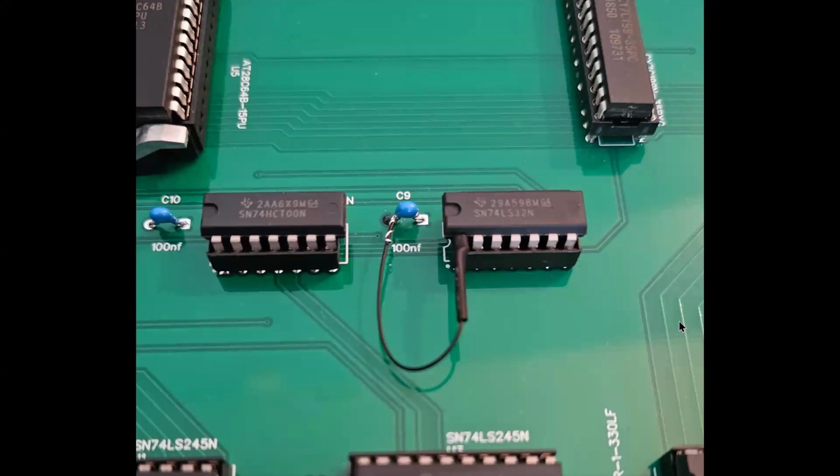Okay, so this is the fix I decided to do. I basically had two choices. I could have scratched out the trace that was there and rewired this pin, which was the read-write signal pin, on the underside of the board to ground. Now, I always try to prove out my changes before I do them. So I had some extra board and I tried to scratch out the trace, and I really wasn't happy with how that was working out.